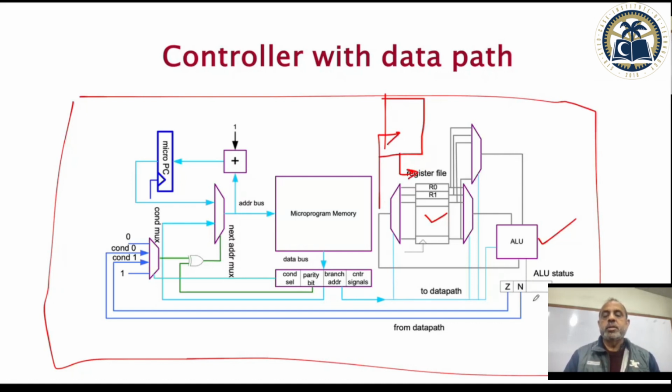This is called the processor status register. Every processor has a status register which will say if the previous computation has resulted in an answer which is 0, it will set this flag. If the previous computation has resulted in an answer which is negative, it will set this flag. An overflow flag, a positive flag, a negative flag, a 0 flag. So the processor status register has bits which are specific to the status of the previous instruction that it has just executed, and they can be used as conditional bits to decide what the processor should do, if you want to.